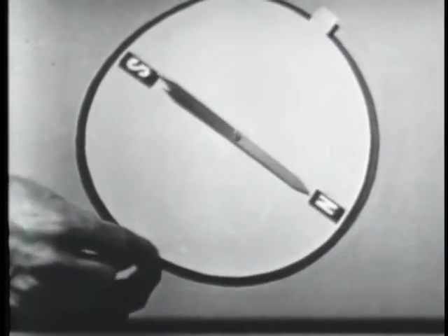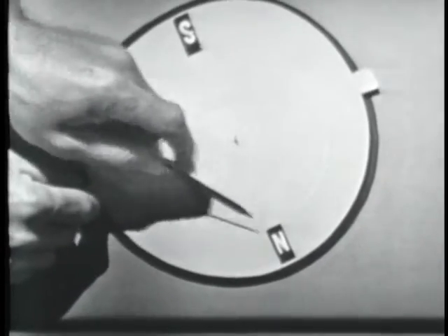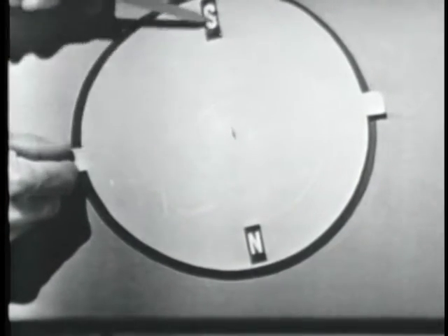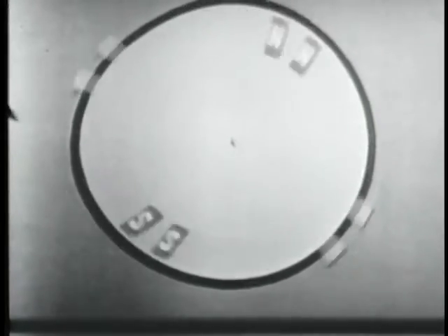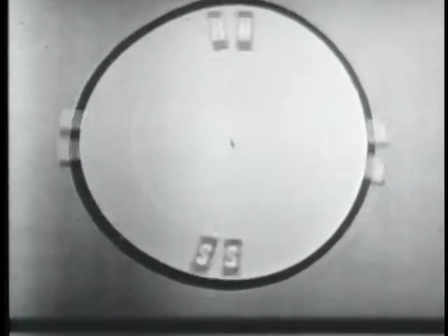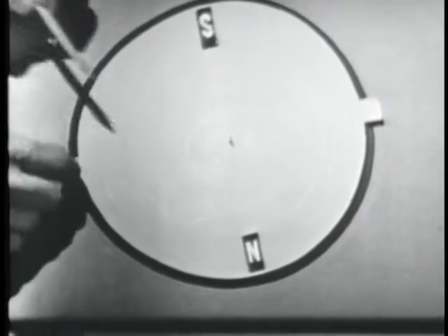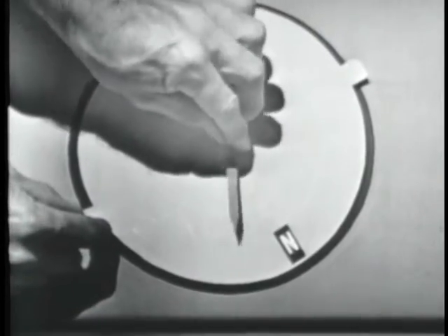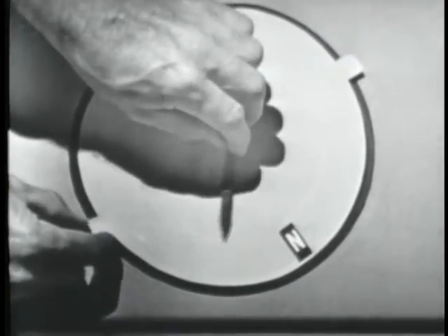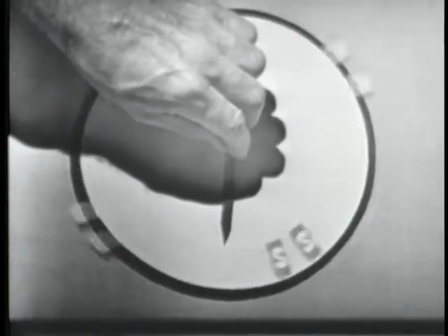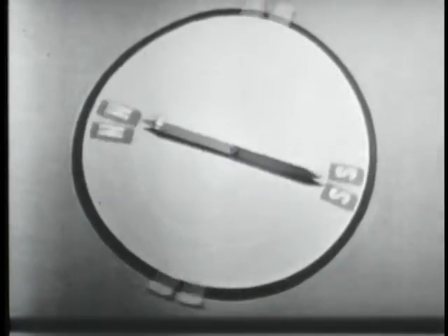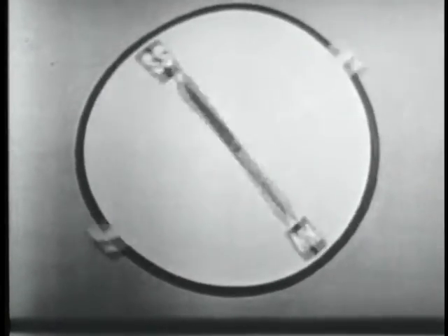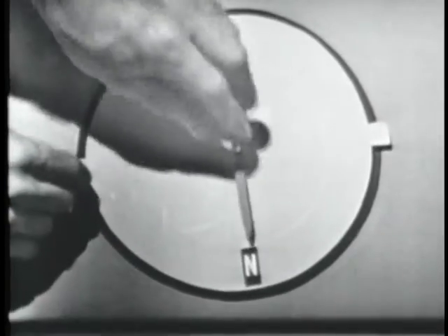What we have here is a cardboard disc, mounted on a pivot, by the way, so that we can spin it, and we have 2 permanent magnets glued to the disc. Thus, if we spin the disc, we have a rotating magnetic field. Now, the principle we want to show you here is that if we take another magnet, such as this compass needle, and put it on the pivot, so it's free to rotate, and we spin the cardboard disc, we have a rotating magnetic field. You'll notice that the compass needle picks up the rotation of the rotating magnetic field, tries to align with it. This is an extremely important principle.